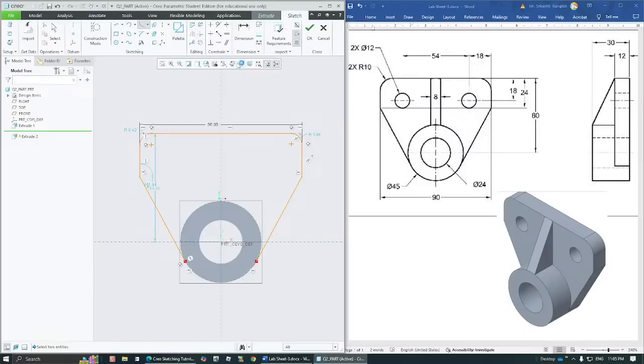Both of them need to have same radius, so let's click on equal to and apply that constraint on these two fillets. So now both the fillets will be of same radius. You can see only one dimension is appearing. On the other side we don't have a dimension, and the equal to symbol is there, which means the radius of both are equal. Let's change this radius to 10. That's what we need over here. The total length is remaining the same. This is the same.